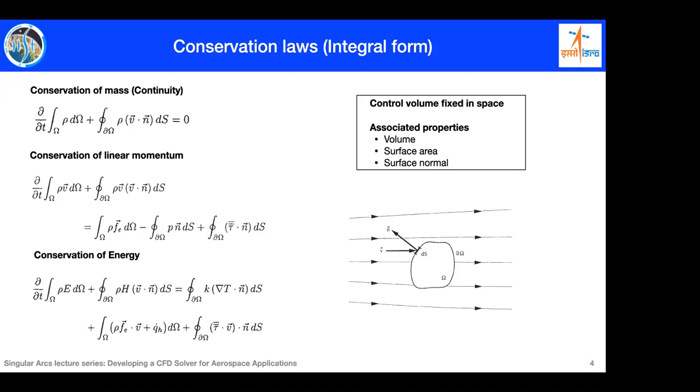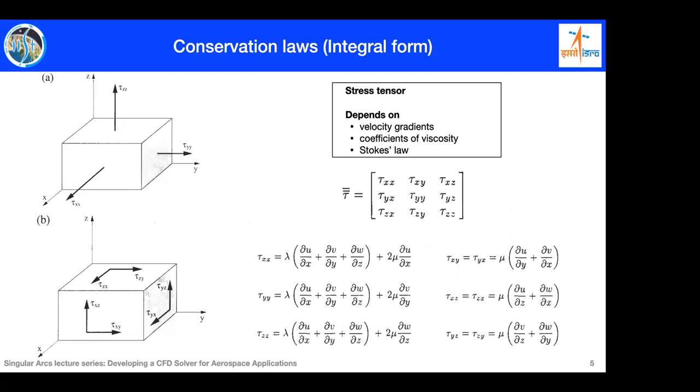Apart from theory, when you go to actual implementation, these things also matter. Then the viscous flux used in our momentum conservation equation consists of stress terms, so velocity gradients are also required. These gradients also play an important role. This is just to give an idea of what terms are involved in the governing equations.